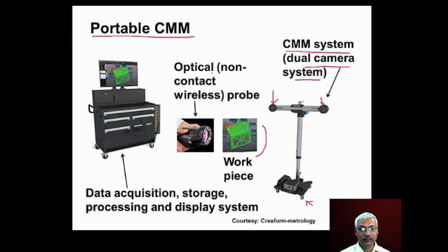And then this optical probe takes the images from the workpiece, and that data is sent to the data acquisition, storage, processing and display system. There is a dedicated computer system with the software. All the data obtained by this optical probe is transmitted wirelessly to this data acquisition system. This system, after acquiring, will process the data, and then the results are displayed on the monitor.